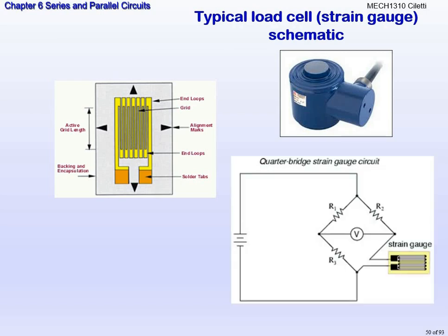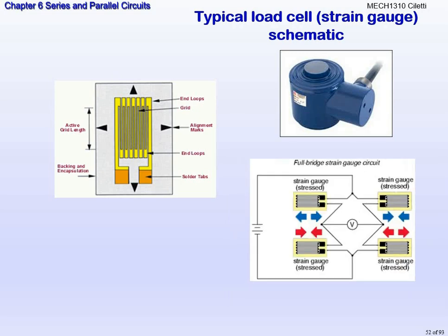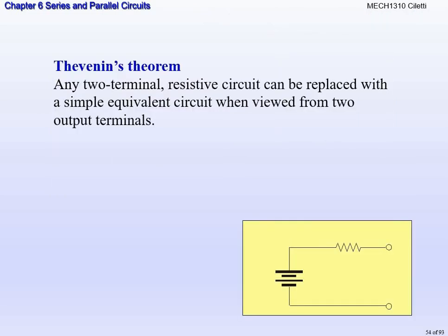Okay, so just different ways of what they look like and where we put them, and it's doing other different calculations for us as well. But this is how all four apply, so on a scale or something like that. If you use a full bridge, a full bridge means every single one of those resistors is a variable resistor. Where the one we just did was a single. The calculation we did with the thermistor was single, but for a scale, you're going to use a full bridge.